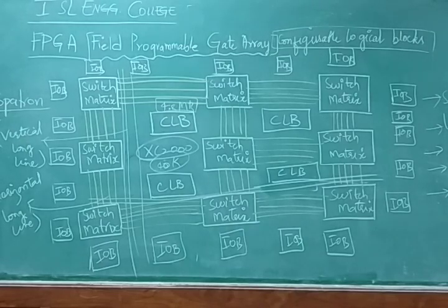It is a truth table stored in an SRAM which provides the output for the combinational circuit made of logic blocks. So the main realization of the logic gates of the combinational circuitry can be done in SRAM by using lookup tables. FPGAs, CPLDs and PLDs are all designed using computer aided design, meaning CAD tools.